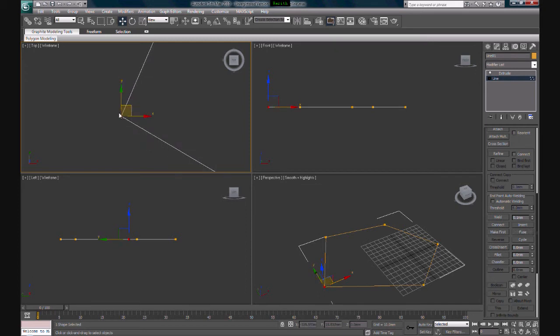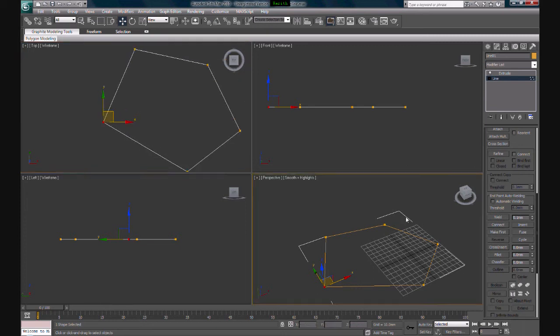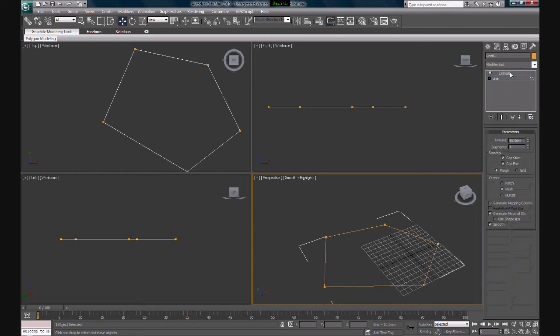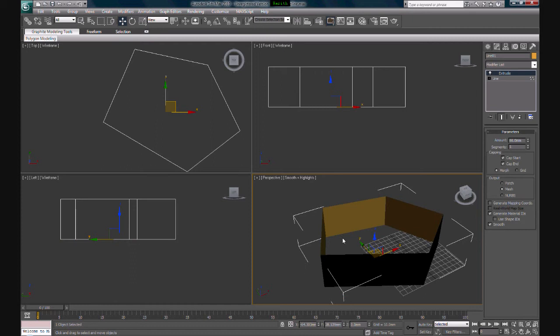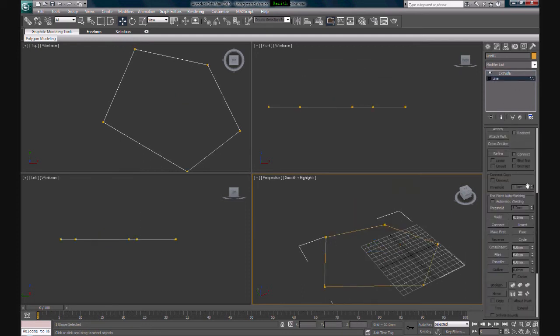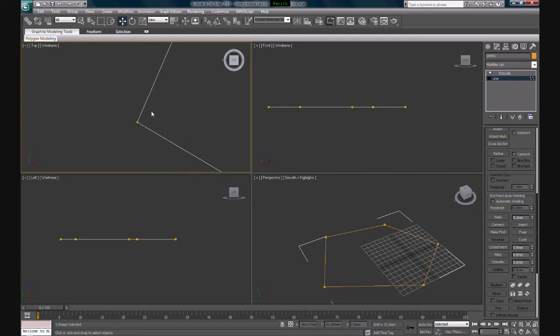So now it is important for you to weld it, because if you don't weld it, I'm going to show you. If you don't weld it, I'm going back to extrude. It will still be paper thin extrusion, where there's going to be a void in the center. So I'm going back to line. The way to avoid that is, after you fuse it, you must weld it.